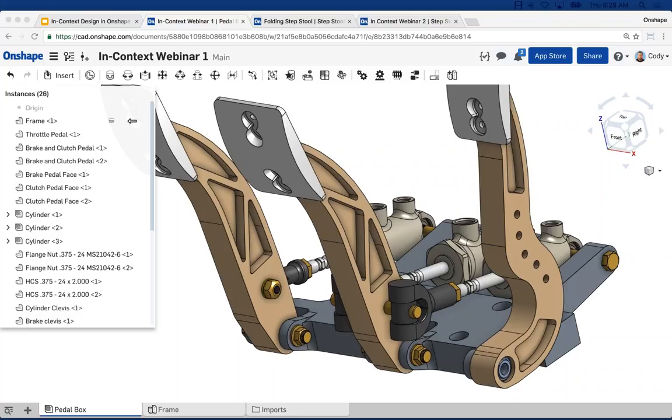Forgive me if that's not answering it. Would you want to isolate coupled with InContext, especially on larger assemblies? That can absolutely help, yes. And I would say, again, just make sure that you have the appropriate parts hidden or shown. Isolate is a good way to get that quickly, but whatever techniques you prefer, make sure that you have the right part showing and in the right orientation when you either edit a context or update it. Those are the two stages where it's really critical.